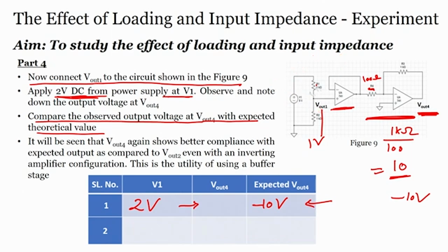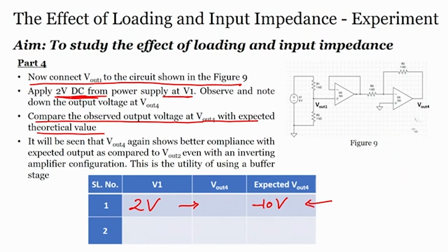First we connect the potential divider, the buffer and the inverting amplifier. Here you see we have not used a non inverting amplifier, we have used the inverting amplifier. The ease of the inverting amplifier compared to the non inverting amplifier is in the selection of resistors.